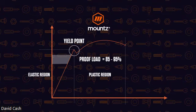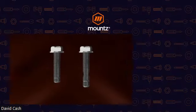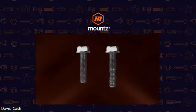And so we want to make sure that we are within that window or below for us to be able to use that fastener correctly. And so this would be an example of a fastener that was stretched past its yield point, and a fastener that is not.